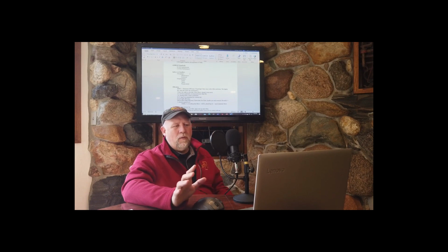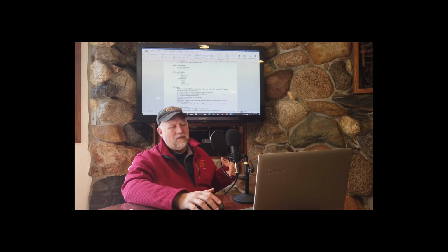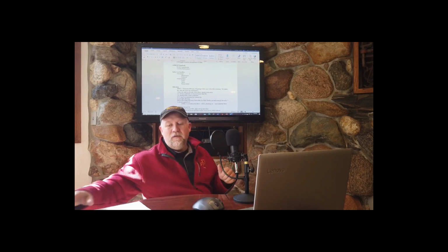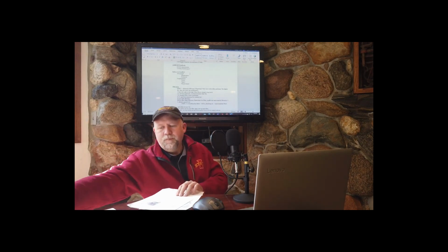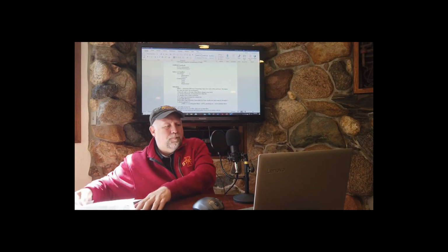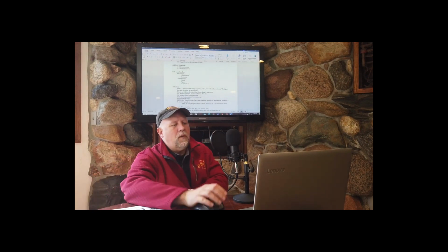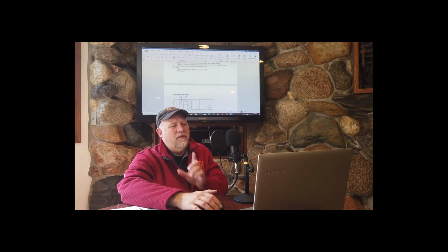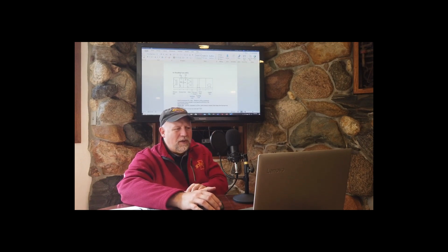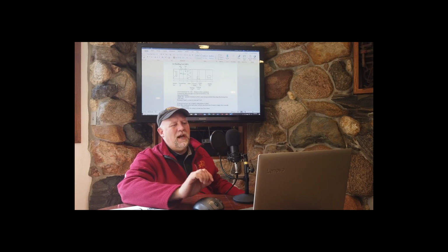ASHRAE standards, important ones. ASHRAE standard 62, that's the outside air requirements. ASHRAE standard 52, that's the MERV ratings. All right, and these on the filtration, this is just kind of a summary of the stuff that I just went over. Now let's look at air handlers and kind of schematic.